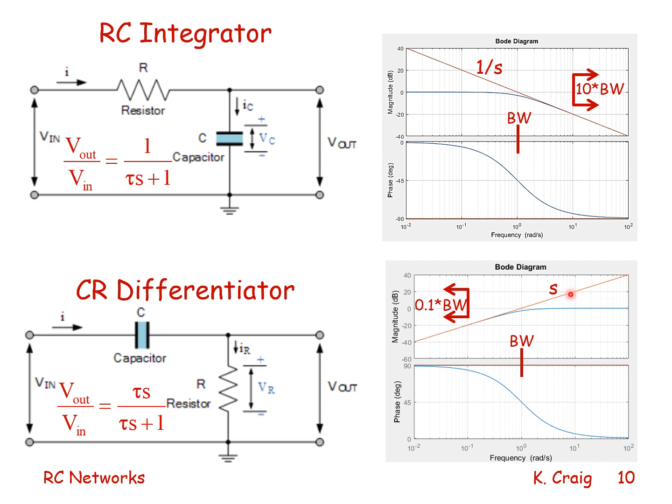Now, S is like D, means take the derivative. The frequency response of S, a differentiator, a derivative, is shown by this straight line. And we see that at low frequency, at 1/10 of the bandwidth and below, the CR filter and the differentiator, the frequency response plots, are identical.